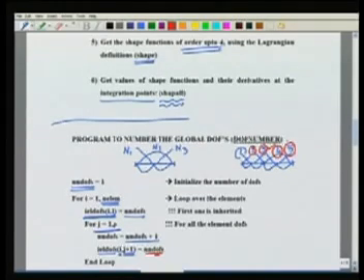So you see that this way, for any p, we can keep on constructing these global degrees of freedom, and assigning to the element this connectivity between the element 1, 2, 3 up to p plus 1 to the global ijk. So this I am going to do in a loop. Once I have done this, I stop my loop over the elements, and I have essentially the one-to-one correspondence between the local degrees of freedom in the element to the global degrees of freedom in the domain.